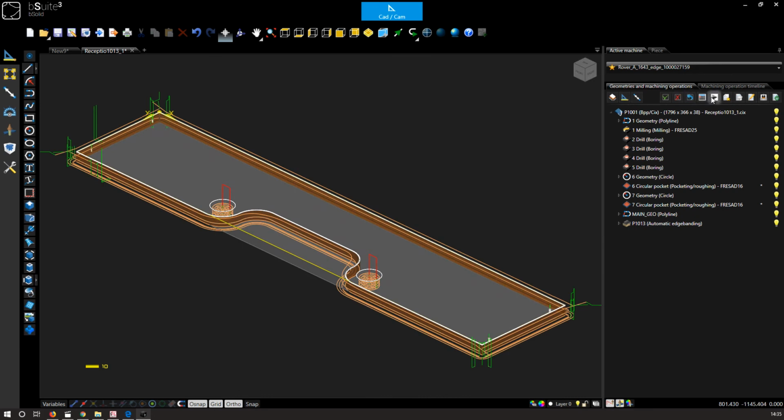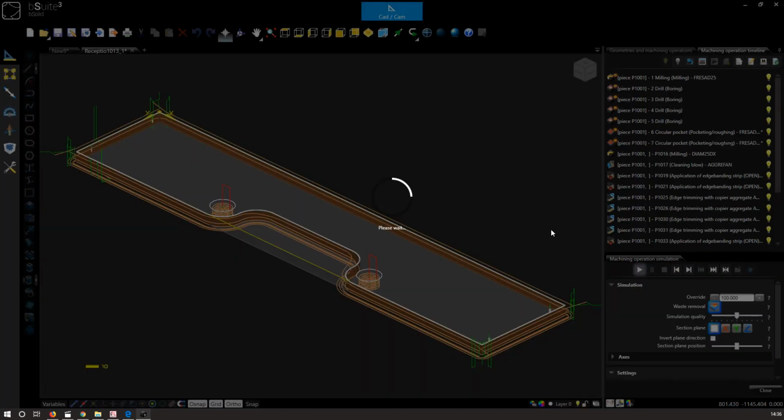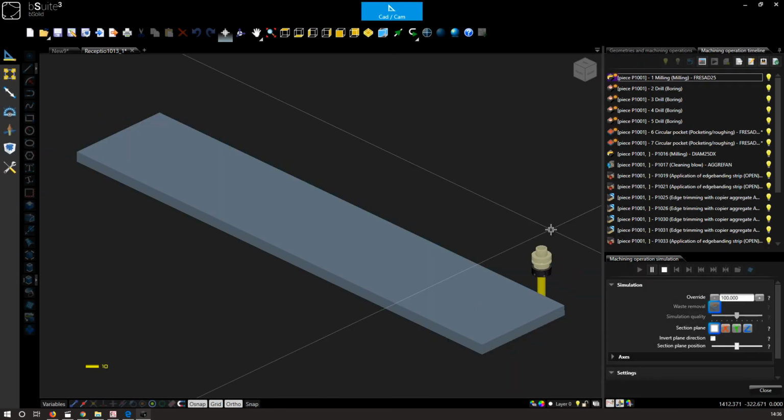So again, there's a bit more involved in this process. The material is slightly thicker. We may need to have additional format contours to machine through this in 2 steps rather than 1. Again, that would be a setting that is set within IMOS and would happen automatically because it knows the thickness of the part. So it would automatically create a 2-step pass. So here's our first step. This is a little quicker now. I've not moved the speed down so much. And there's our second formatting pass. Put a little less stress on the cutter.